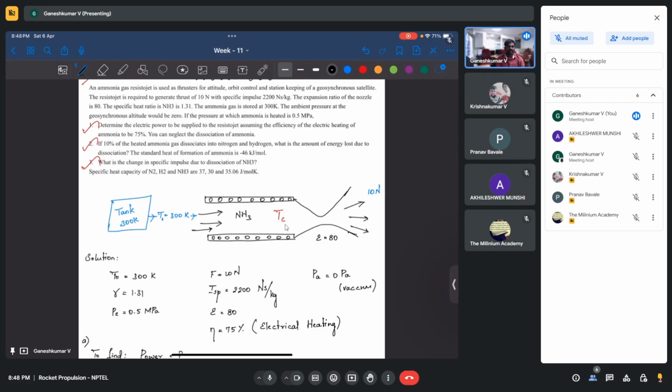There are different parameters, as you said. There is going to be the amount of heat released, which is going to increase the sensible energy part, and there's going to be the amount of CP rise or CP decrease, which is going to affect the temperature again. And there's the molecular weight of the mixture, which will be difficult to accelerate in the nozzle.